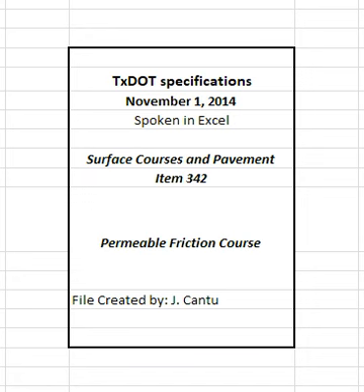2.1.1.2 Micro-Deval abrasion. The engineer will perform a minimum of 1 Micro-Deval abrasion test in accordance with Tex-461-A for each coarse aggregate source used in the mixture design that has a rated source soundness magnesium, RSSM, loss value greater than 15 as listed in the BRSQC. The engineer will perform testing before the start of production and may perform additional testing at any time during production. The engineer may obtain the coarse aggregate samples from each coarse aggregate source or may require the contractor to obtain the samples. The engineer may waive all Micro-Deval testing based on a satisfactory test history of the same aggregate source.